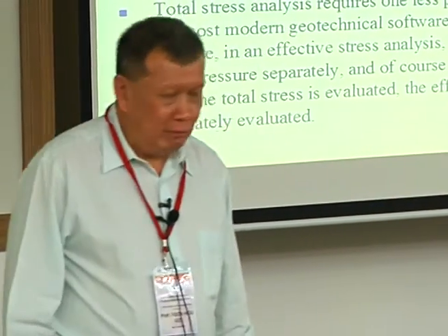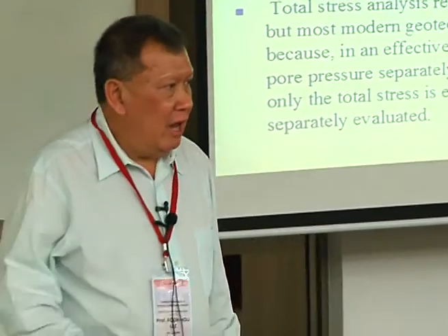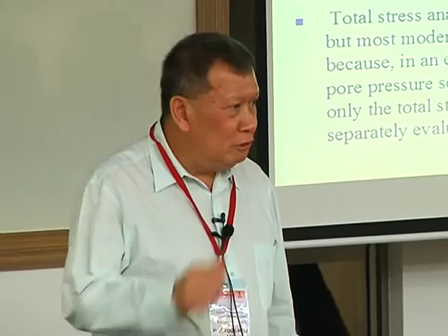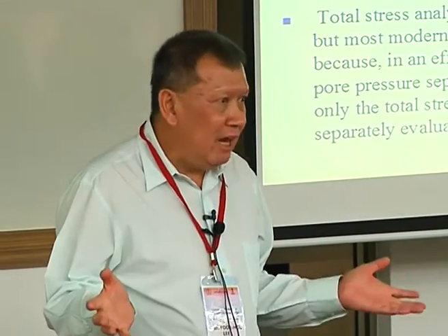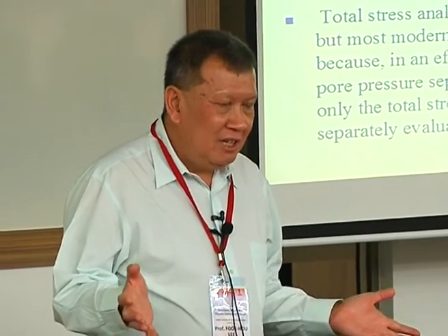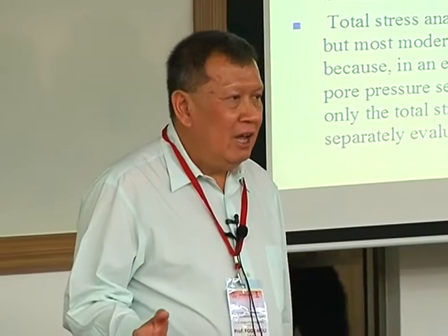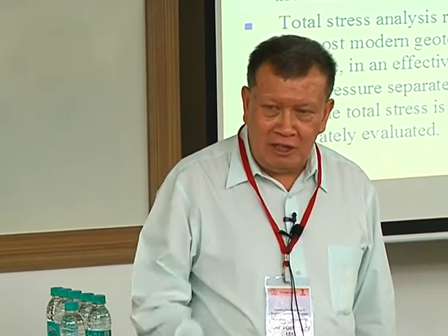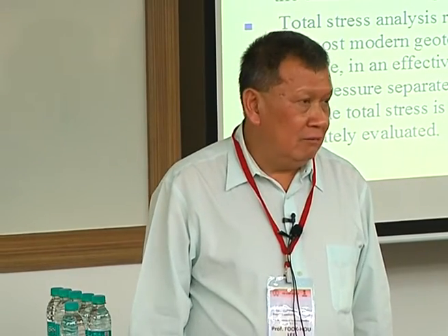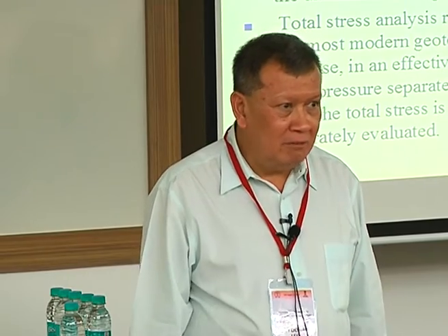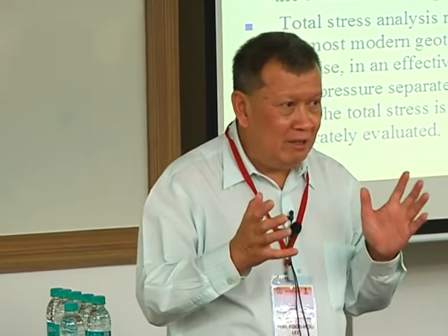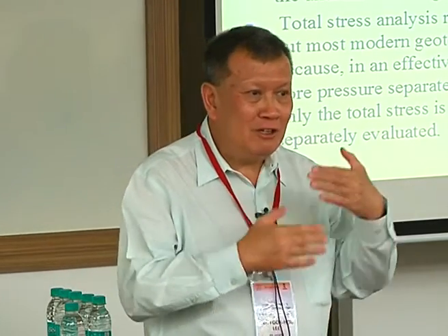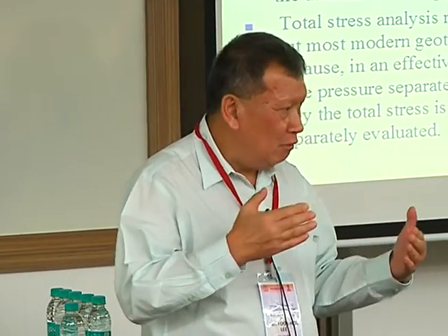Back in the 1990s when we first started using FEM, every soil investigation report was nothing but SPT and UU tests. You can't get anything out of it. It's just basically Cu. There's no c', phi', nothing. And when you asked people to do CIU tests, consolidated undrained tests, or consolidated drained tests, they looked at you like, oh, this guy is talking Martian. But these days things are starting to change, but in a sense, it is an evolutionary change. It's not something that will take place overnight.